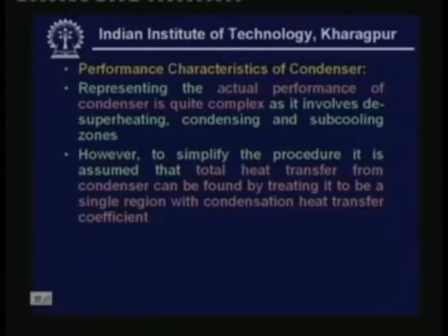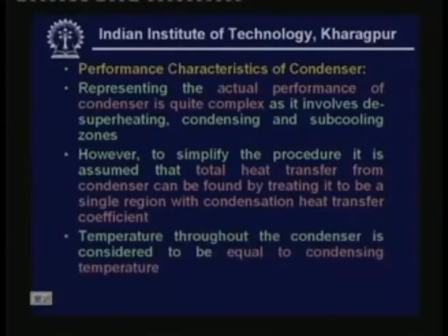So as I said, to simplify the procedure, it is assumed that the total heat transfer from the condenser can be found by treating it to be a single region with the condensation heat transfer coefficient. In fact, the justification for this was given while discussing the condensers. And the temperature throughout the condenser is considered to be equal to the condensing temperature.